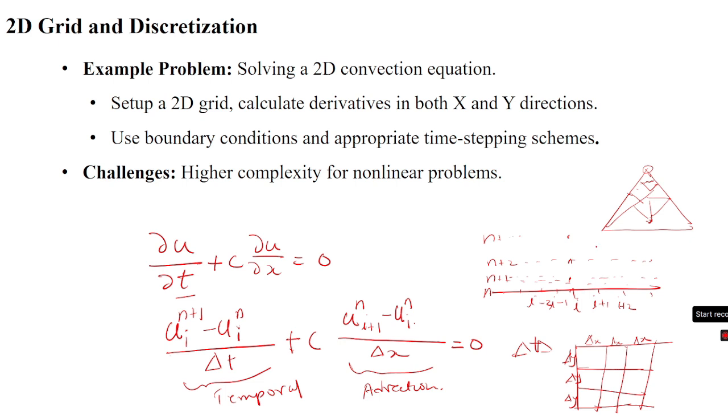in multi-dimensional problems. So if we want to capture the boundary layer in a 3D flow, we should add a prism layer instead of having this particular tri element. In the case of 3D, we should have prism type elements. It means we might create a few layers of grid here, maybe 2 or 3 layers, to capture the boundary layer effectively.